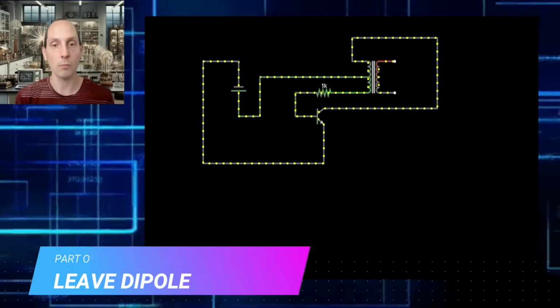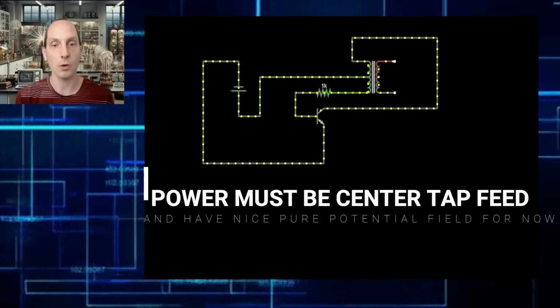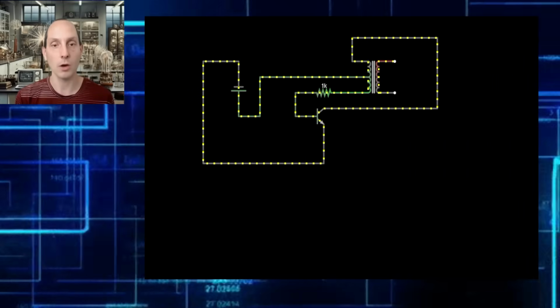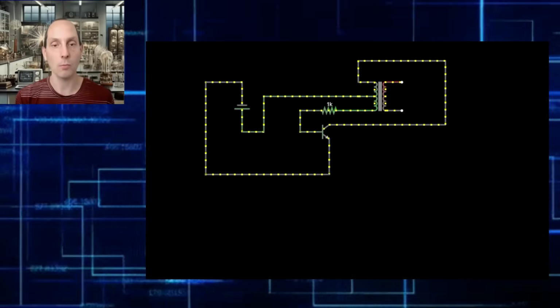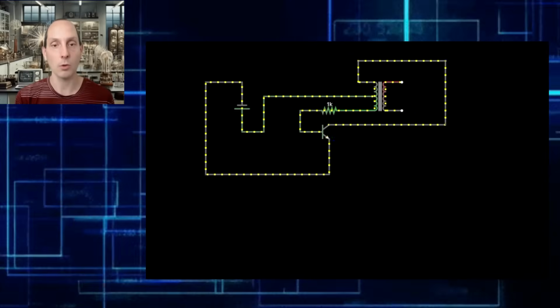Interestingly, certain primitive high-frequency self-oscillating systems exhibit behaviors analogous to time-reverse wave reflection, particularly when operated under free-running, high-Q, nonlinear conditions. One such system is a basic flyback-style Joule thief oscillator, a single-transistor, center-tapped feedback coil circuit.